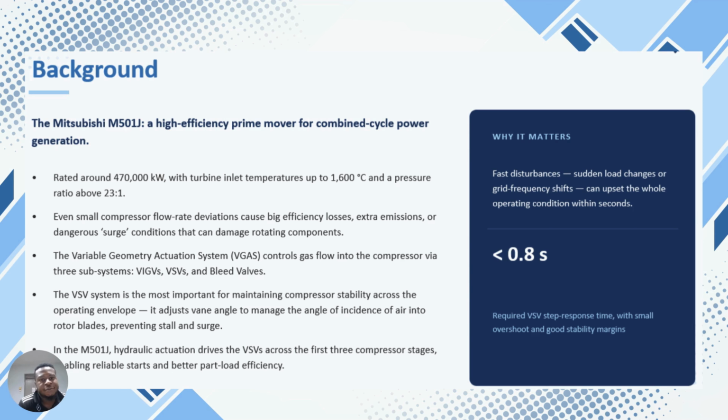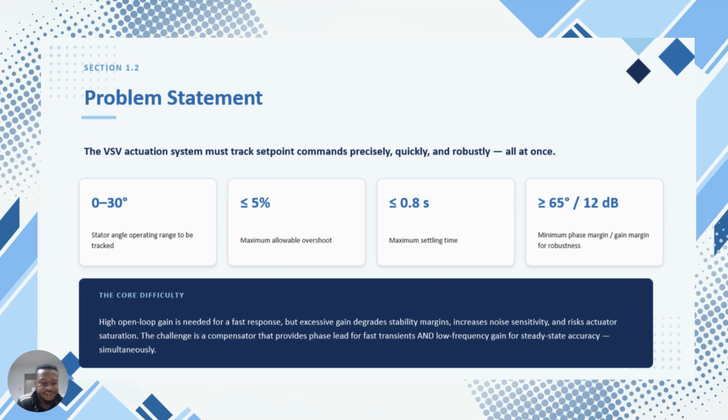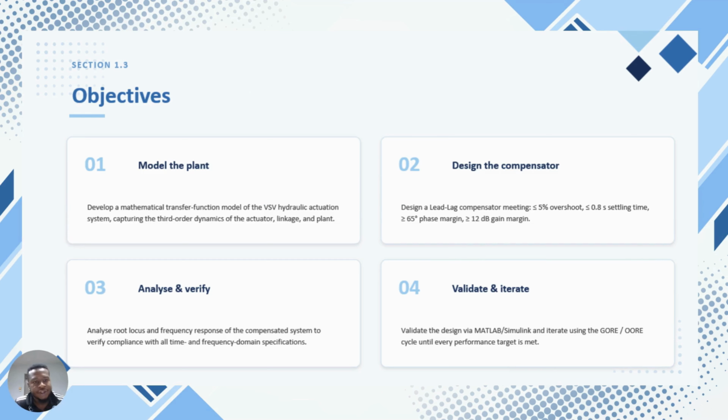The vane angle must remain within its operating range while keeping the overshoot below 5% and achieving a response time of less than 0.8 seconds. In addition, the hydraulic actuator must produce enough force to move the vanes reliably during the operational time.